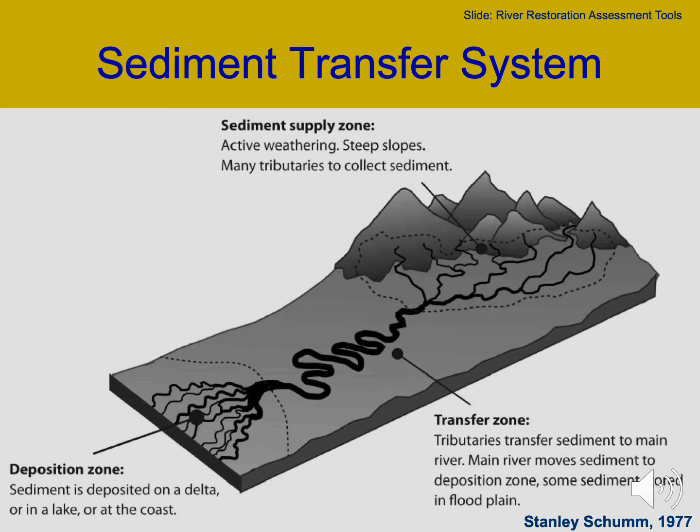The sediment transfer system, a lot like the earlier diagrams, is kind of a schematic of where we produce sediment in the headwaters. Your mid-valley reaches, we consider these transfer reaches where sediment transport capacity is high. Generally, all the production up here moves through rapidly, and then we have our depositional zones. Understanding where your project is in the schematic is another important component of successfully designing a project.